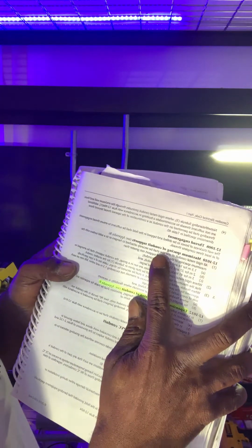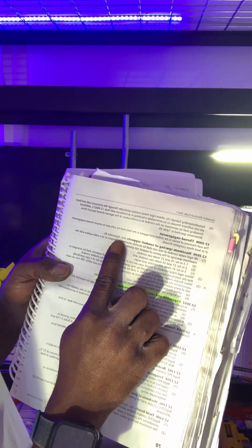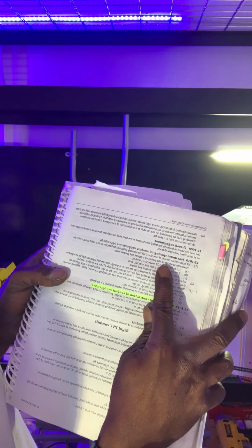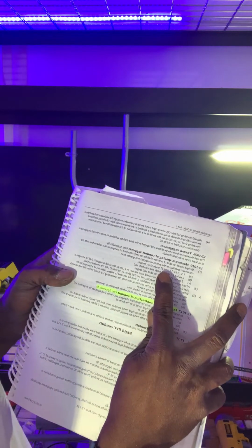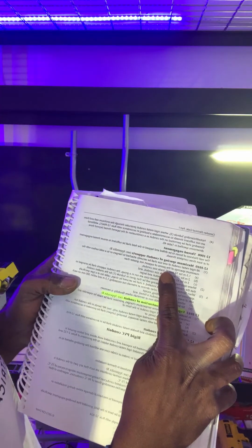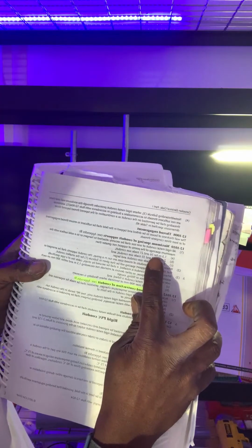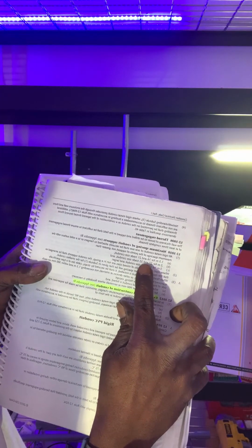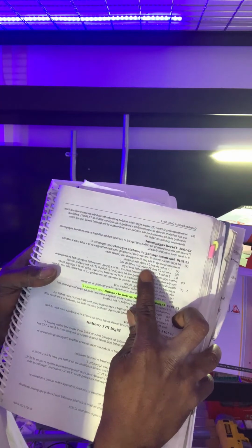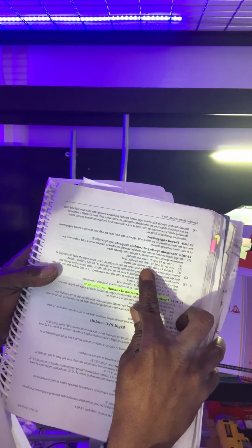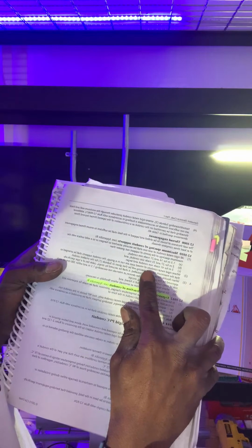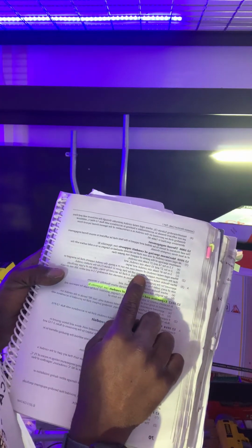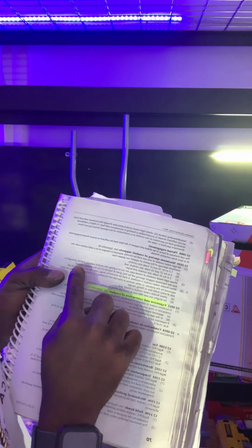12-1010, maximum spacing of conduit support. It also tells you to see Appendix B. Number 1, all rigid conduit of one size shall be securely attached to hangers or to a solid surface with the maximum spacing of the points of support not greater than A, 1.5 meter for 16 and 21 trade size conduit, B, 2 meters for 27 and 35 trade size conduit, and C, 3 meters for 41 trade size conduit and larger. 2, where rigid metal conduit of mixed size are run in a group, the conduit support shall be arranged so that maximum support spacing will be that given in sub-rule 1 for the smallest conduit.